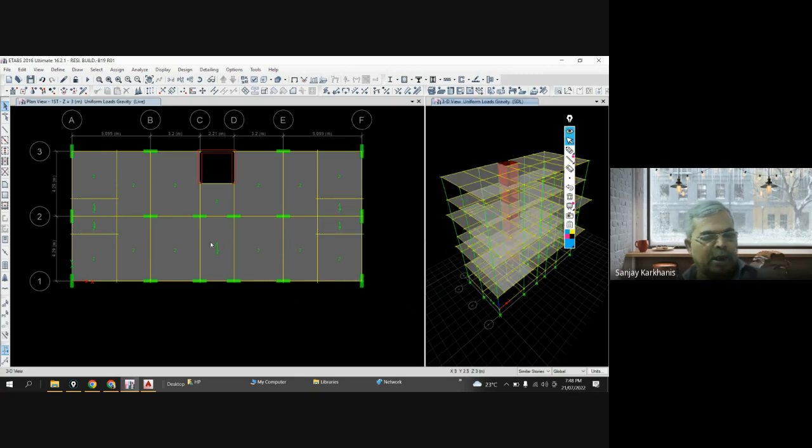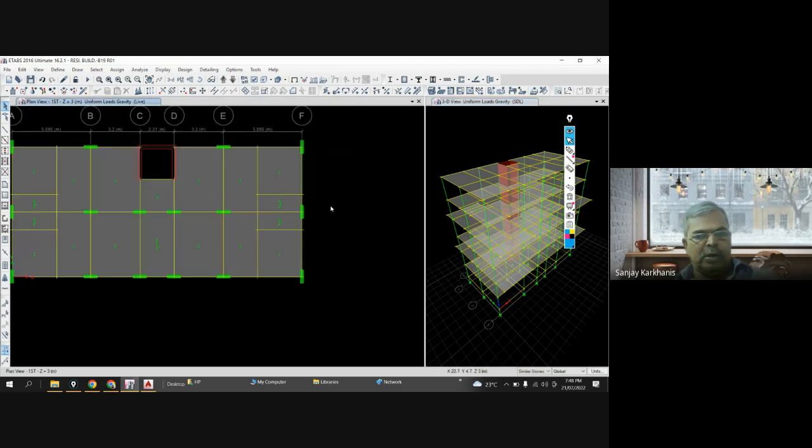Now about staircase. Again, staircase thickness, you don't have to worry about it. Then you will have to go for that calculation that you will have to see. See, this is your going. This is the thickness of your waist slab, and that you have considered something around 200. But the calculation of this dead load is not required, because we have modeled this.